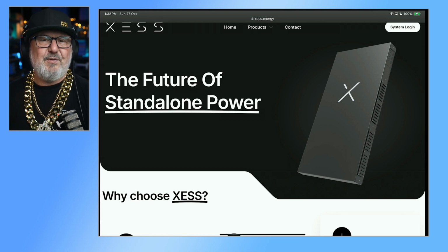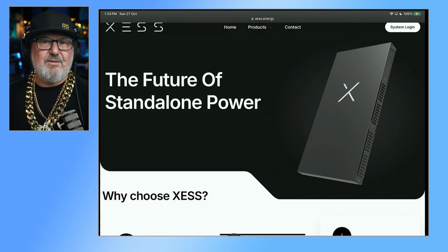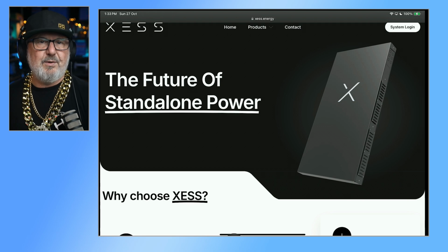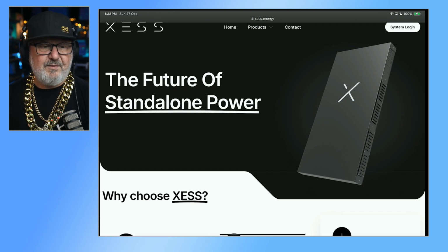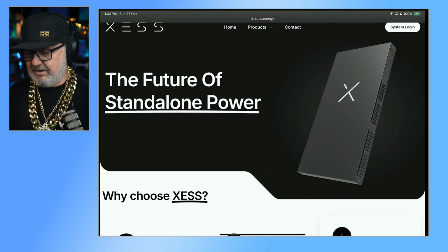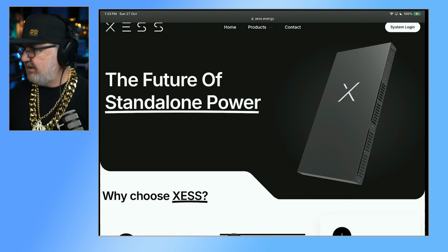And also for off-grid applications, it means that even poor quality backup generators will still mean you have clean power in your home. So that's a huge plus. So yeah, in that box there's up to 4 of their 2.4 kilowatt inverters and 2 of the AERL 5 kilowatt MPPTs. And I believe you can have up to 5 or more of these units. So you can build quite a big system paralleled onto their battery system.